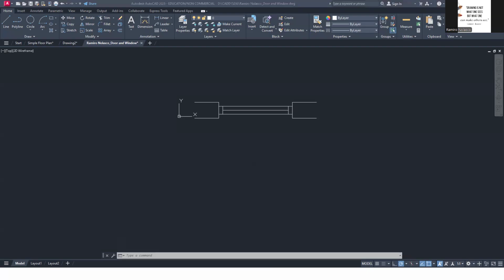It doesn't give you the box. So when you are doing a mirror or when you're selecting objects, do not click and hold. Do not click and hold. What you want to do is click, release, and then you get the box. Do not click and hold. We're used to clicking and holding, dragging, click, drag. We're used to that. Click, release to get the box.